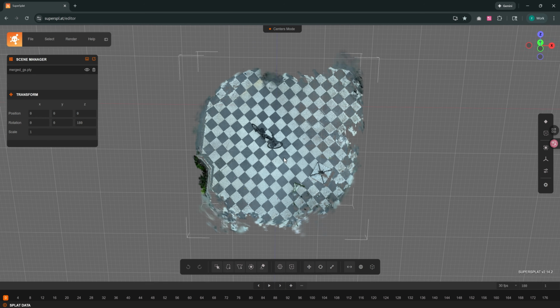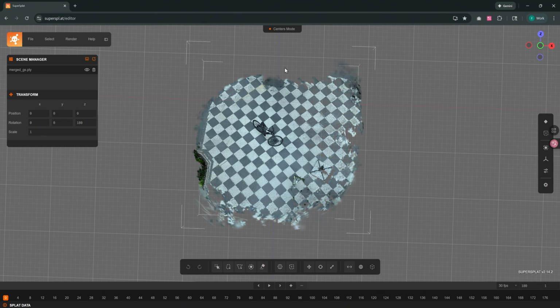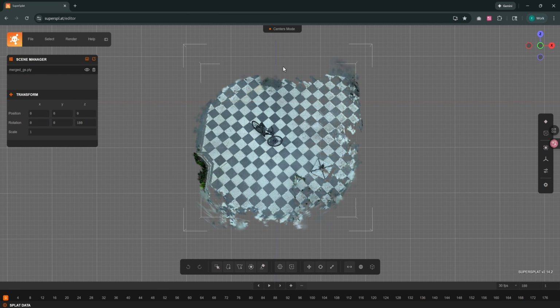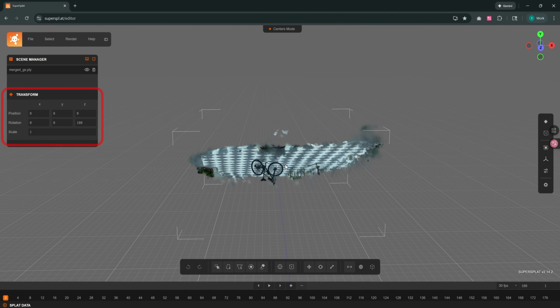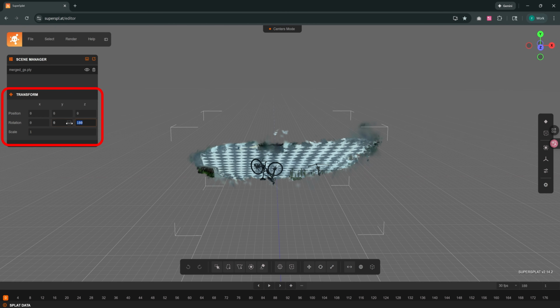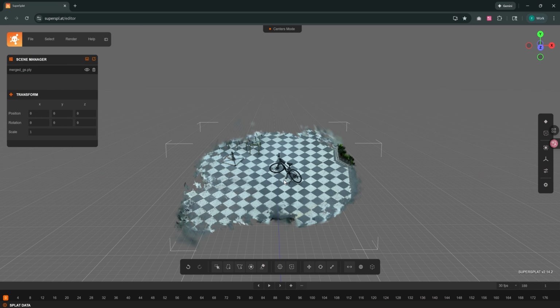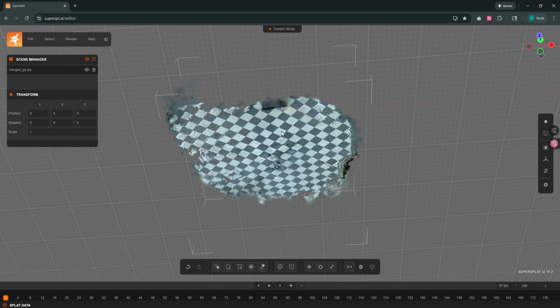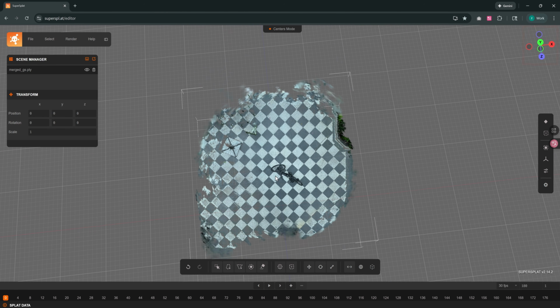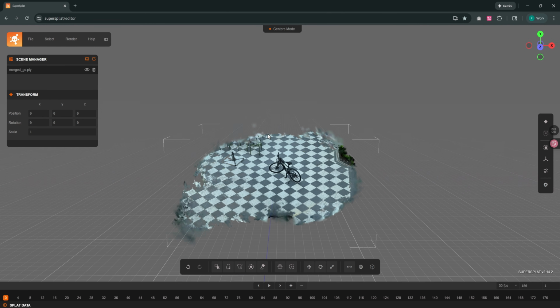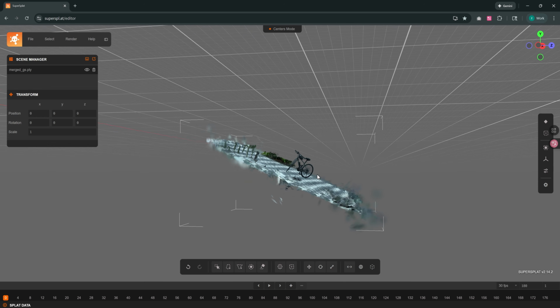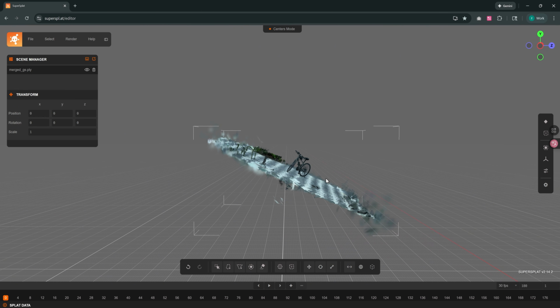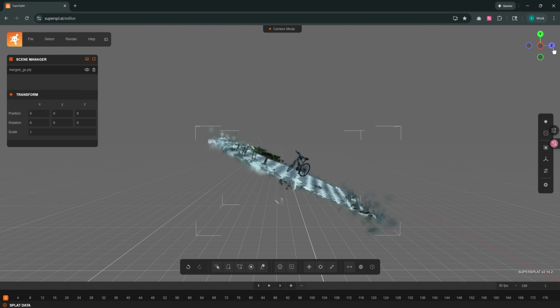Sometimes, when you drag to browse the model, it does not rotate as you expect. This affects the model browsing experience. At this point, you can adjust the model's coordinate system. Here, we first set the z-axis rotation to 0. Rotate the model to align the coordinate system diagram in the upper right corner of the model. You can see that the model does not align well with the coordinate axis and looks a bit tilted. It needs to be rotated by some angle along the x-axis.